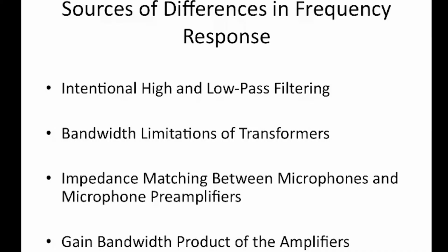And what I think is extremely interesting is the changes in frequency response that happen because of the combination of the particular output impedance of the microphone you were using and the input impedance of the mic pre itself. A lot of people don't think about this, but when you plug a microphone into a mic pre, you're creating a new circuit. They're interdependent, and the mic pre will change the way that the microphone performs, and as a result will change the sound of that microphone. So the input impedance of the mic pre will have a big effect on how the mic itself actually sounds.